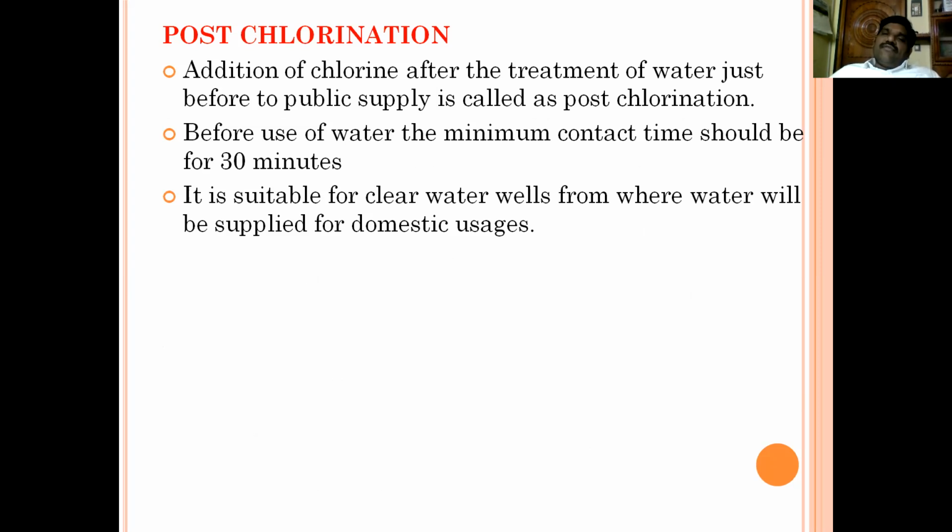Post-chlorination means addition of chlorine after the treatment of water, just before supply to the public. Normally, the minimum contact time should be 30 minutes, and it is suitable for clear water wells from where water will be supplied. This is called post-chlorination.